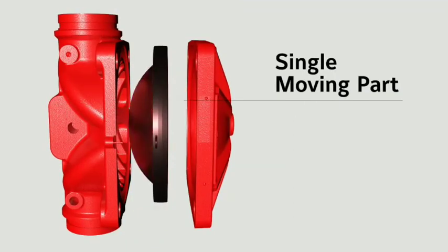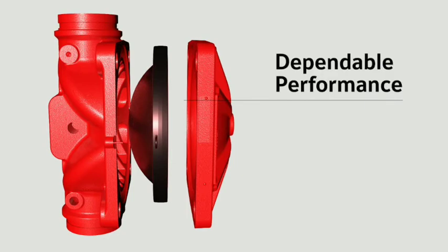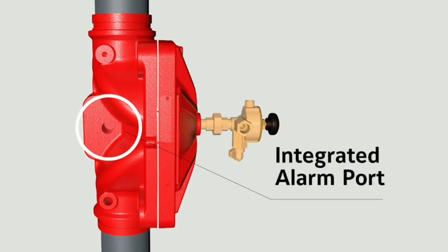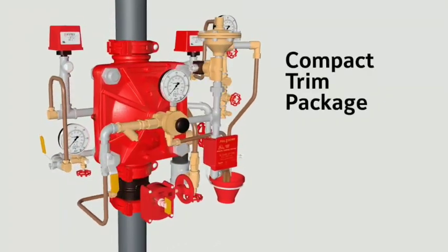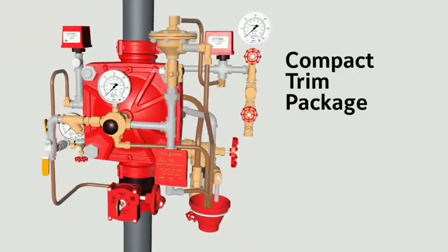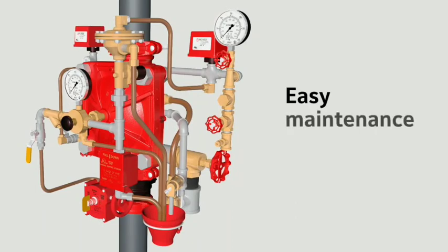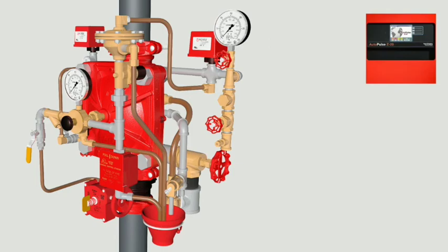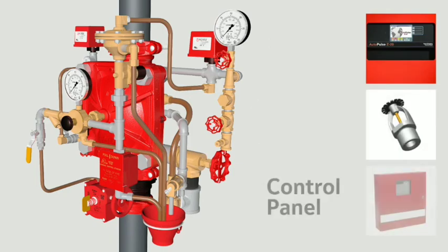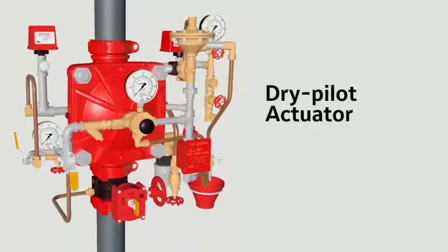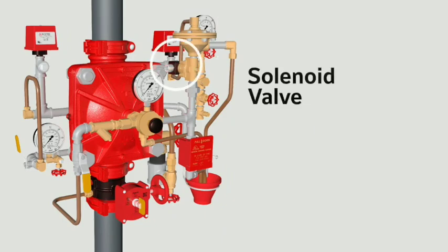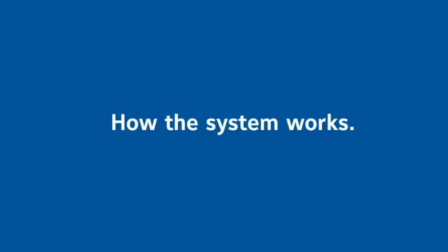Pressure switches are used to sense a change in pressure, and open or close an electrical switch when a predetermined pressure is reached. A bellows or diaphragm is used to sense the change of pressure, expanding or contracting in response to an increase or decrease of pressure. Figure 1.3 shows a diaphragm type of pressure switch. When pressure is applied at the inlet and the preset pressure is reached, the diaphragm expands and pushes the spring-loaded plunger to break contact.